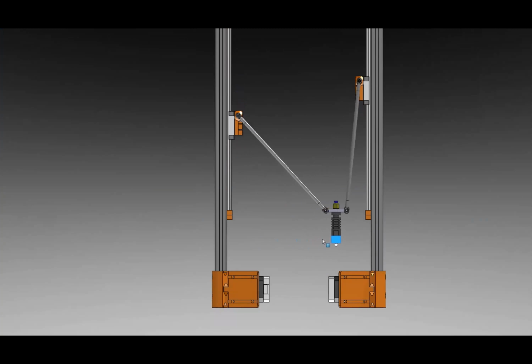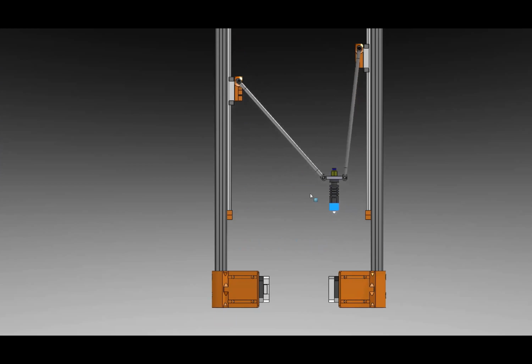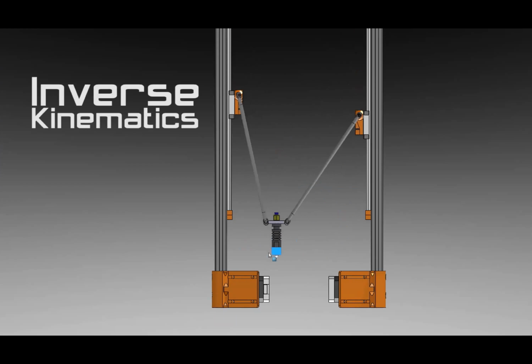Luckily, by also moving the other carriage at the same time in the opposite direction, we can move only in the direction desired. This seems simple enough, but the 3D printer has to look at each position it moves to and figure out what position the carriages have to be in to get to that position. This is called inverse kinematics, and it's one of the reasons Delta printers aren't more popular.